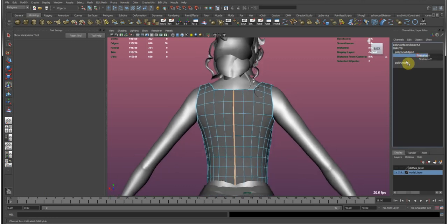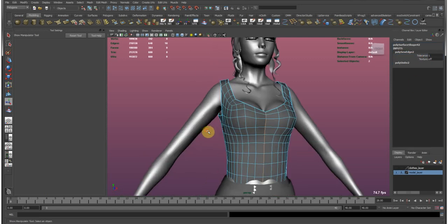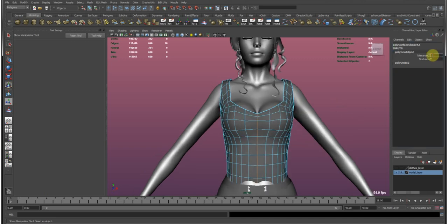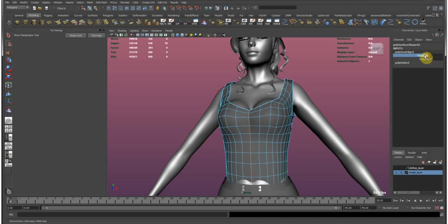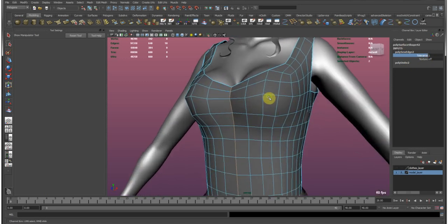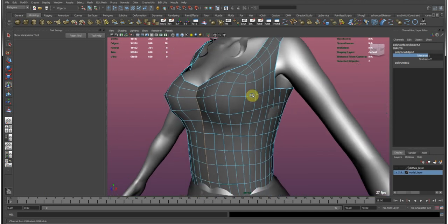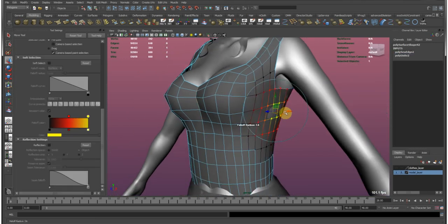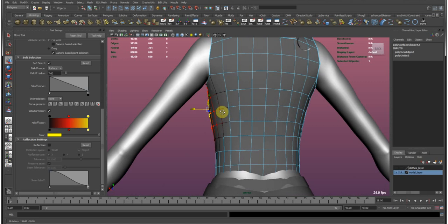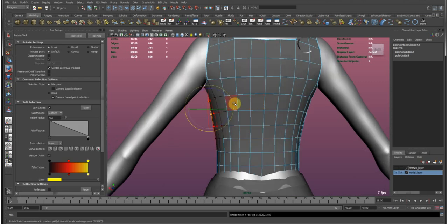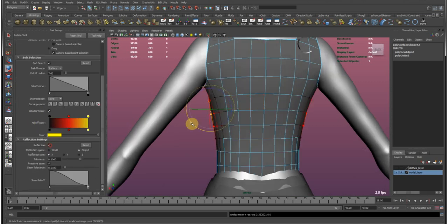If nothing happens, grab the tolerance in the channel box and middle mouse button drag, or just hit the one arrow. Maybe you can put in a 2, it doesn't matter. But 1 is the maximum if you middle mouse button drag the attribute. But 1 works quite well. Oh, undo that and turn on reflection.